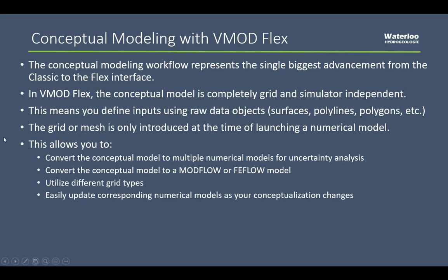So in Visual MODFLOW Flex, we actually support two workflows, the numerical and the conceptual modeling workflow. With conceptual modeling workflows, you essentially build a conceptual model that's completely grid independent, and then at the end of the conceptual modeling process, you define a grid, and then you simply merge the two together. And then on the other side of the conceptual modeling workflow, you essentially will have a fully functioning numerical model. And you can actually use that conceptual model to spin off multiple different iterations of your conceptual model using different grids, different grid types, and that type of thing.